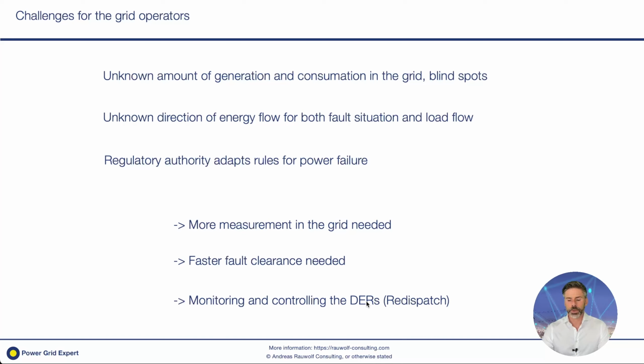Especially here in Germany, we started, I would say, 10, 15 years ago with DERs. In the very beginning, they were hardwired to the networks without any control in between. And over the years, we saw there are problems. There's the influence on the frequency, which is most crucial for the stability of the network. There's the influence on the voltage level in that network. So we absolutely have to have a way to control these DERs.